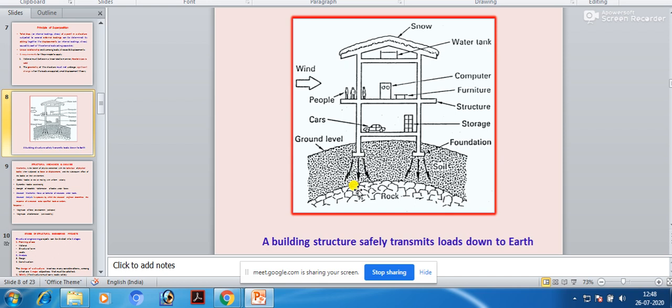So you see the contiguous elements we have spoken about. Contiguous elements means this: from this roof slab the loads are coming to these beams, from these beams the loads are coming to these columns, from these columns the load is getting transmitted to the foundation, from this foundation the load is getting transmitted to the soil, and from the soil the load is getting transmitted to the rocky stratum. And this is what a complete structure looks like.